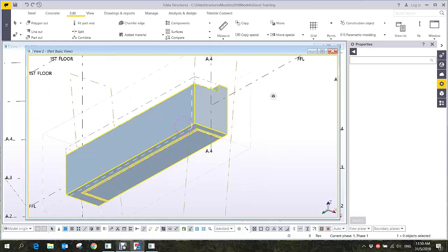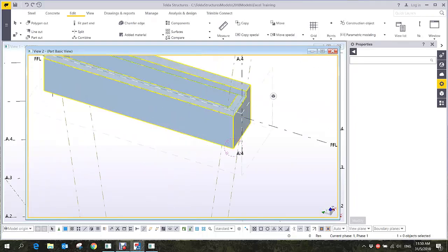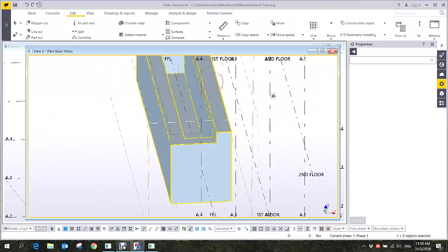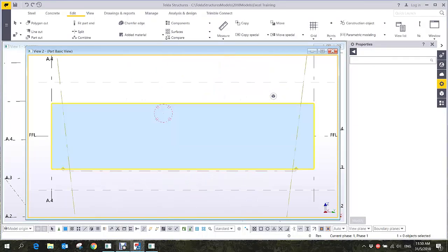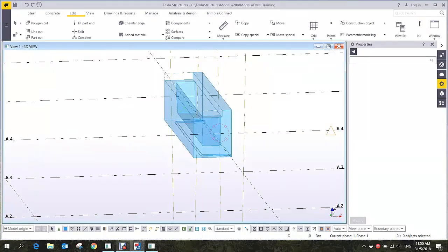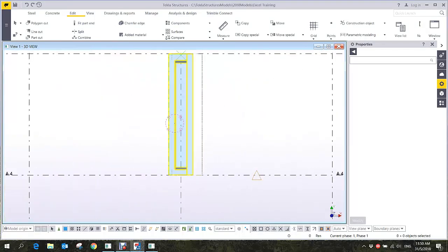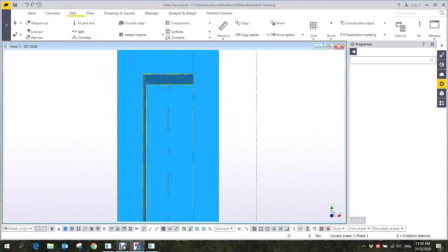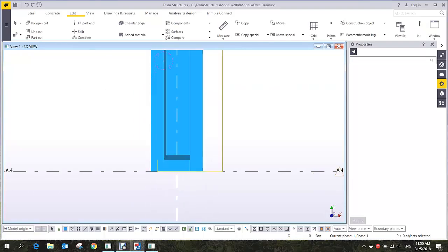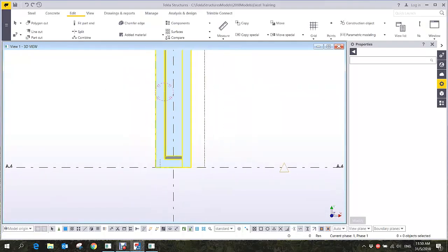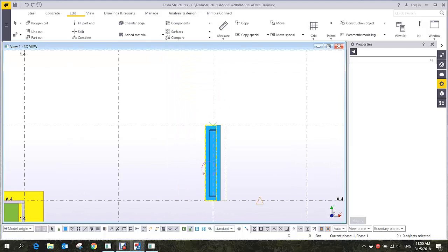So later we can add the reinforcement. So this one is one way of doing it. Another way is you can put one wall, and then you add that one as a cast unit for different part. Okay, but again, this one should be okay as well. Straight, and then this one is okay. If you go to the top view of this one, so this one you can see here, it's already with the slanting for demolding, right? Because if you don't put that one as a slant, then difficult to demold.